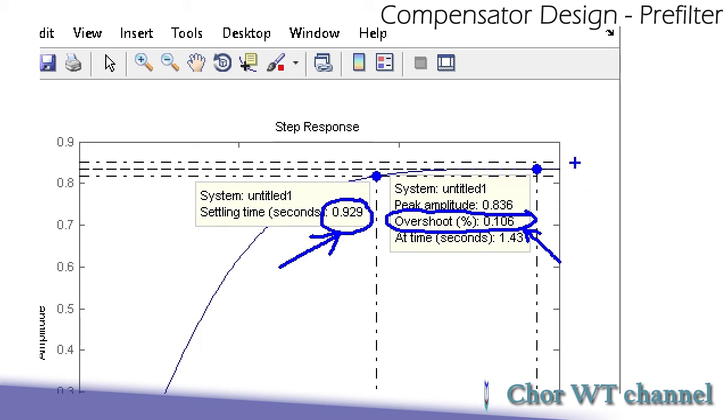So now you have a choice here. After you have implemented your lead lag controller or other forms of controller, if you have identified that your zero is the main cause of the difference between your calculated or estimated values, as opposed to the generated or simulated performance, you can consider the use of a prefilter to minimize the effect brought by the additional zero introduced while you are designing your controller.